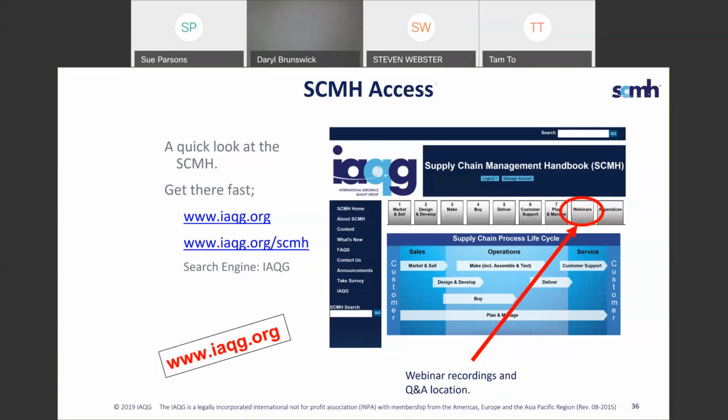And something I didn't address, which this leads me to, you can do product PFMEAs from receiving to shipment, or process PFMEAs. You can say, everything has to go through the grinding room, so I'm going to do grinding as a PFMEA, and I'm going to connect all my PFMEAs together to have my product PFMEA. When I was in automotive, we sold 1,000 SKUs.